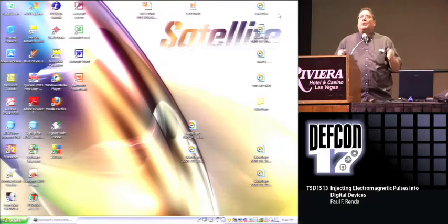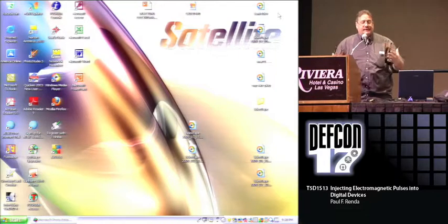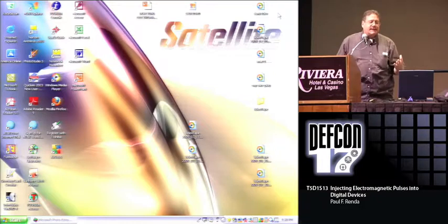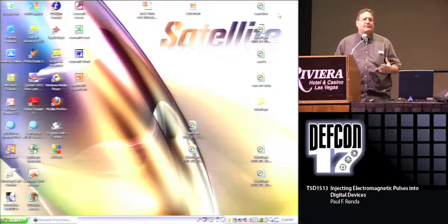The 10th video was actually my pulsing a Pentium 166 megahertz laptop, an old laptop, and the hard drive I already fried. And I pulse it, and I boot it up over Windows 95 diskette. I'm pulsing it, and it stops. It dies. It needs manual intervention. So I stop it, I bring it up, and I use a Red Hat Linux boot disk. Pulse it, it stops. Basically what that shows is that if you inject electromagnetic pulses into digital devices, they react irrespective of the operating system, actually irrespective to some degree with respect to the CPU, but they do disrupt the device.